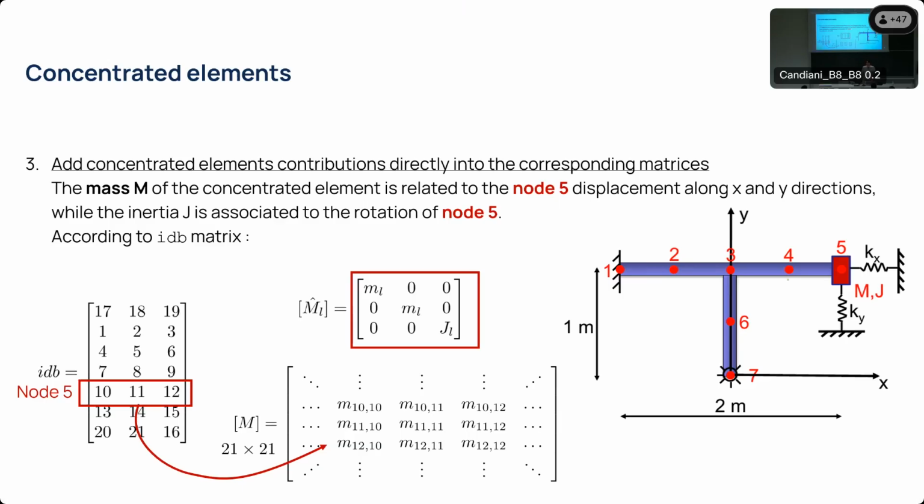I know that with Professor Zasso, you also saw how to use the extraction matrix, so a rectangular matrix which has the dimension of the various global coordinates on the rows or columns, depending on how you rotate or transpose it, and on the columns or the rows, the various degrees of freedom of the nodes or the coordinate or the element you are trying to add the various quantities to.